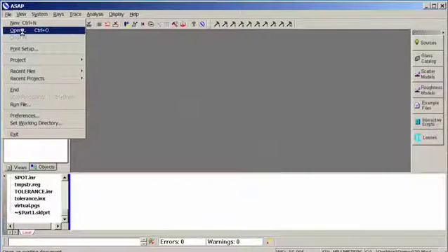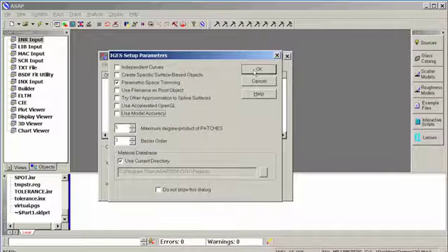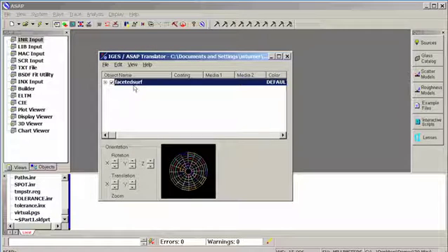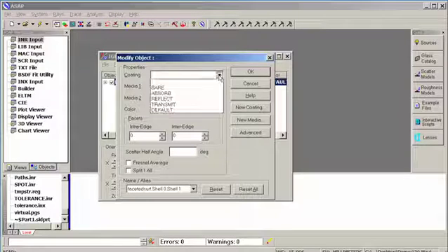And I'm going to open a file, and in this particular case I'm going to open up a faceted parabola. We'll accept most of the defaults and just click on OK. Within my CAD file, I named this object faceted surface, and when ASAP imported that IGES file, it remembered that information. And what I want to do is modify the properties to apply properties universally across this object.